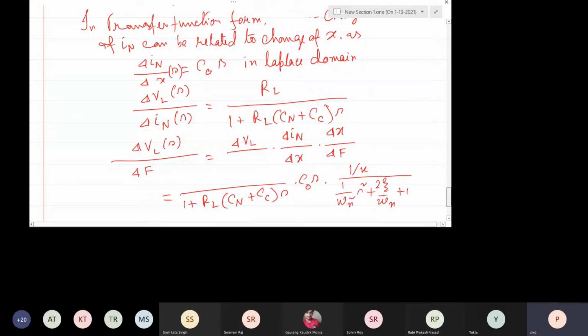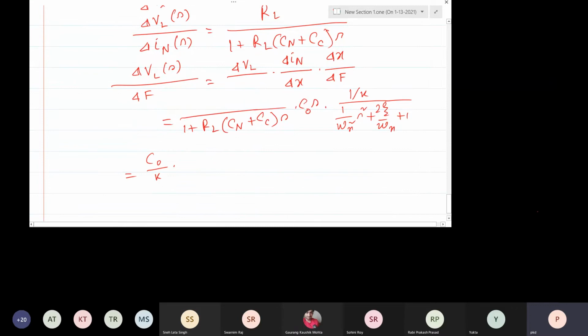Now if you analyze this circuit, we have this transfer function. In this transfer function, you can see there is an S in the numerator. S in the numerator means basically it's a differentiator. So that differentiator will kill the zero-frequency response, that DC response of the device. Ideally, we would have a steady state output corresponding to a steady force. But if we want to measure this voltage, then this happens. So we don't have it.